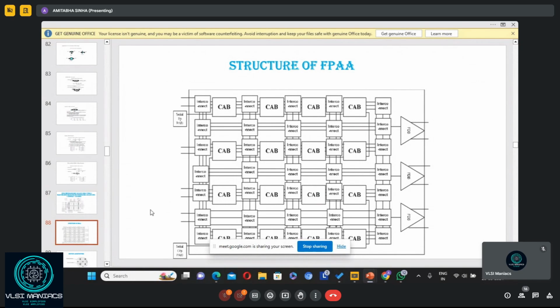So if you want to change the circuitry, all that you have to do is change your program, or, keeping the same circuit, change the parameters. What are the parameters? The value of the resistors, capacitors, etc. So you just change those. And to change the value of the resistors, all that you have to do is change the clock frequency. And clock frequency can be changed by changing the counter value.